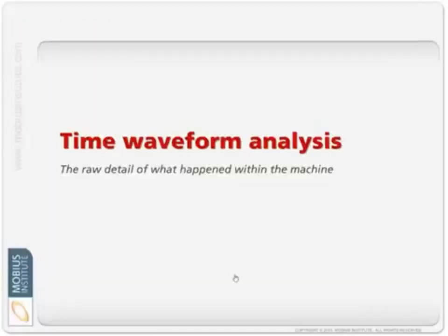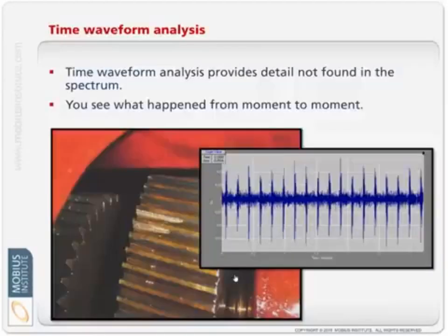So let's keep going. So far we've learned that the spectrum does break all those frequencies up into their individual components so that we can see faults like, specifically, unbalance, misalignment, looseness, foundation problems, and so on and so forth. Now, that's great, but time waveform analysis gives us a perspective of what's happening that you can't really get from the spectrum alone. So imagine, if you've ever recorded your voice and looked at that waveform from your voice, this is what we're talking about.